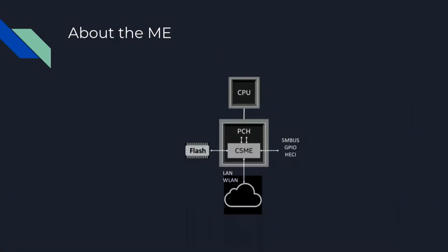So first of all, what exactly is the management engine? There's been a lot of fuss about it being a backdoor and everything. Well, in reality, whether it is or not depends on the software that it runs. It's a processor with its own RAM and its own IOMMUs and everything sitting inside your south bridge. It's not in the CPU; it's in the south bridge. So when I say this is going to be about the 6th and 7th generation of Intel chips, I mean mostly motherboards from those generations. If you run a newer CPU on it, it will also work for that.